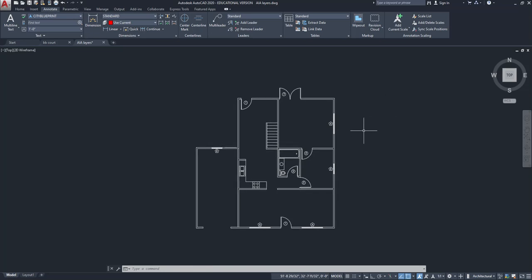All right, so let's talk now about creating dimensions. Without getting too much into the theory behind dimensions, let's talk about how to create a dimension style and then how to apply dimensions to objects in AutoCAD, okay? So dimensions, under the Annotate tab here, are the little tool palette to the left of our text tool palette. They're another form of annotation, and they describe drawings in terms of giving them actual numeric definition, right? So the dimension of things. They tell us the project's size, essentially, okay?